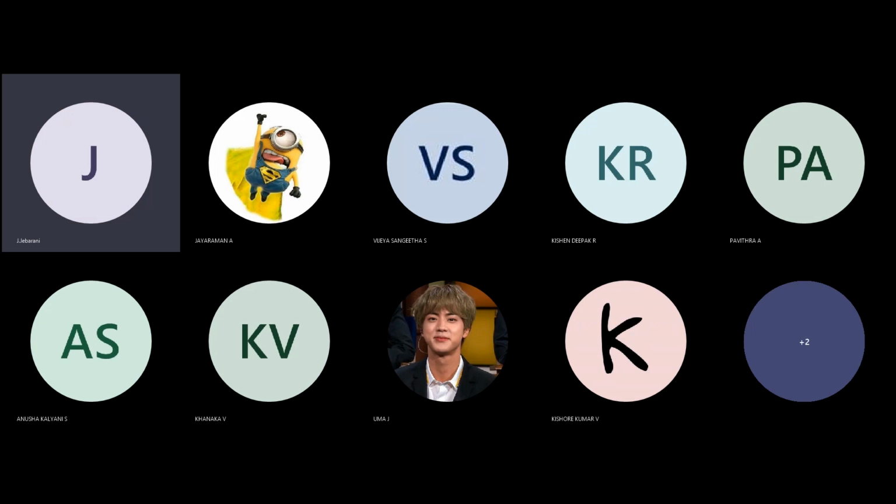The incoming water displaces the melt, which is pushed into the secondary cavity. The secondary valve is closed for hold and pack, so water can be expelled through the cavity or by evaporation.